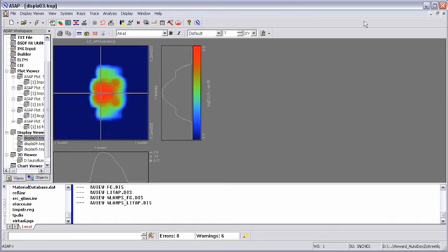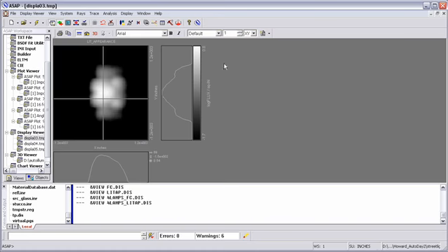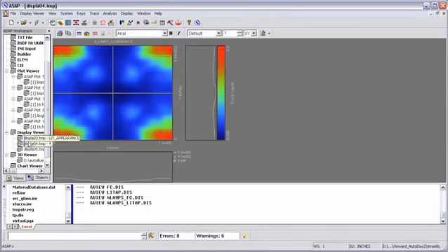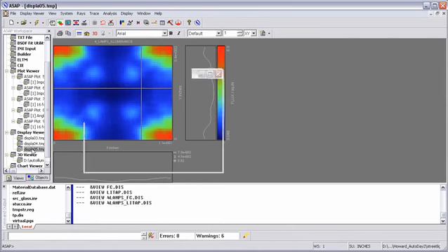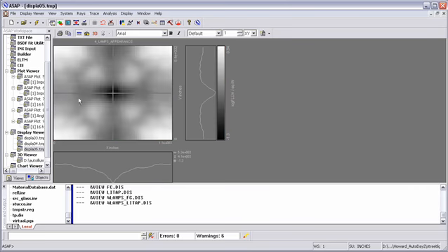We also have each one of those plots in a 2D plot viewer where we can go in and interrogate each pixel individually and find the values of the points. Now, this particular plot happens to be a plot that's been adjusted to simulate what you might see with your eye, as though you were hovering above the pattern. This is an isolux plot of the 4 lamps, and then this is the plot of the 4 lamps positioned over a roadway section.